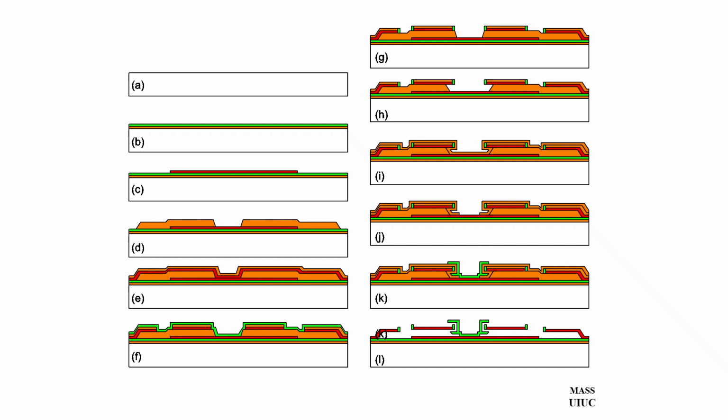This is the third and yet most complex rotor structure. It consists of bushing with silicon nitride anti-friction ring. Let me explain how this is done. You have a silicon oxide and you grow a silicon nitride layer, and this nitride layer serves as an underpinning. You deposit a polysilicon layer. It's red, and this is the first sacrificial layer material.